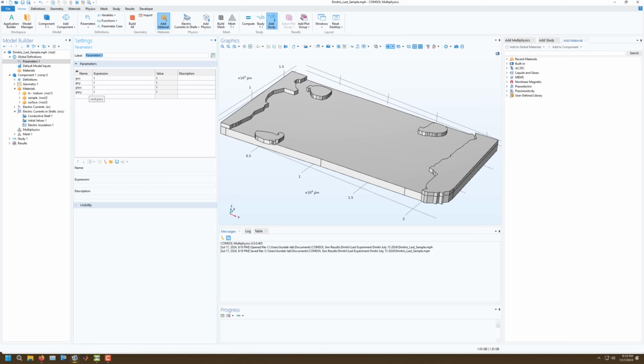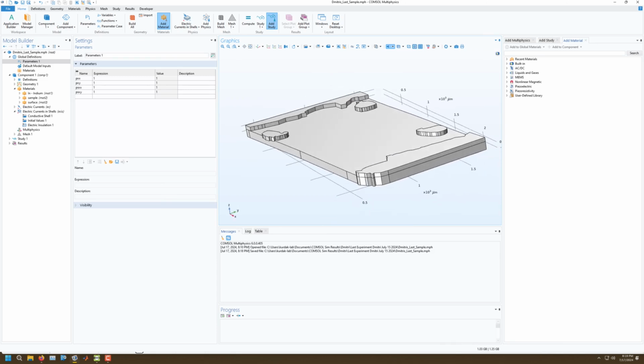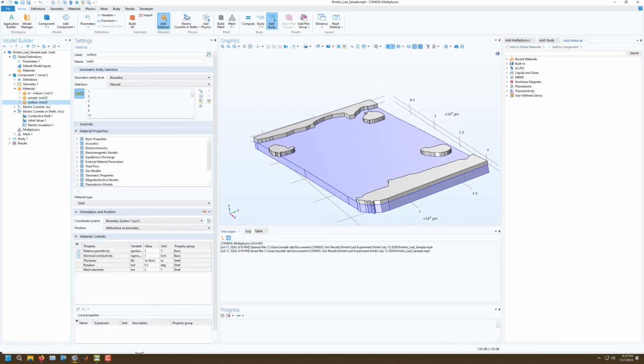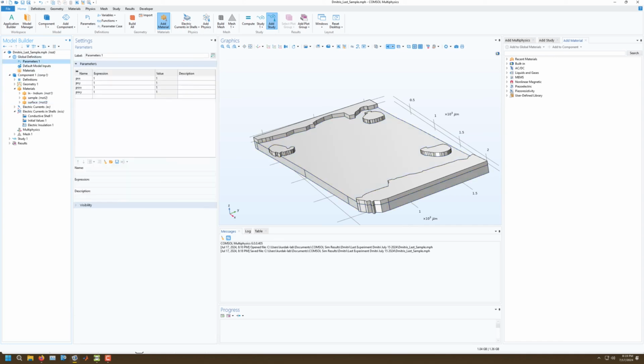The resistivities, you know, they're just ohms for the 2D case, but COMSOL doesn't do that. They do 3D. That's why we define the thickness down here. So we know what the thickness is. So all we have to do is convert to the 3D resistivities.